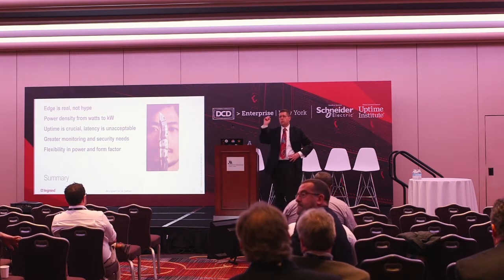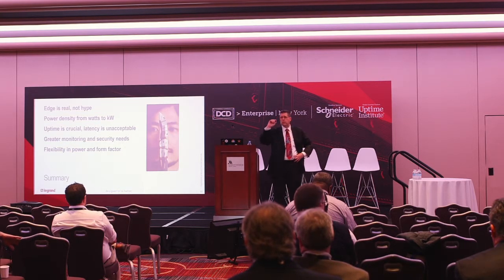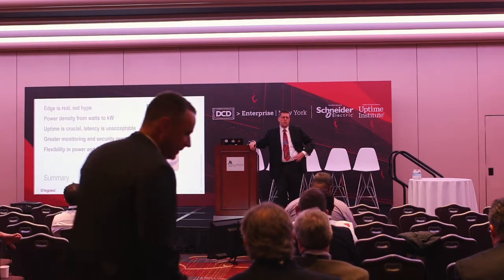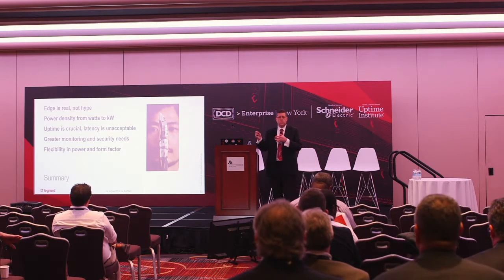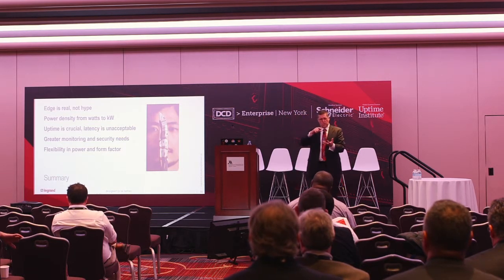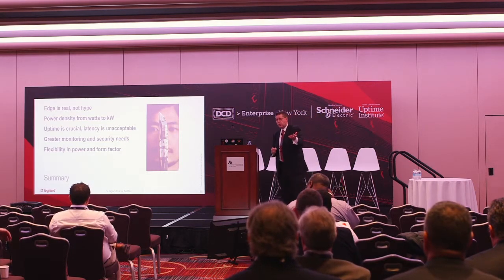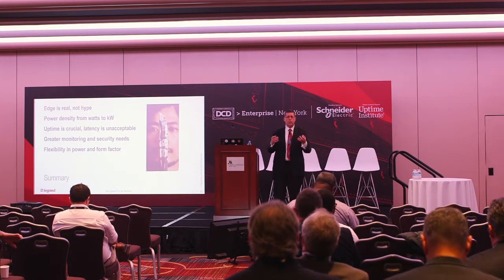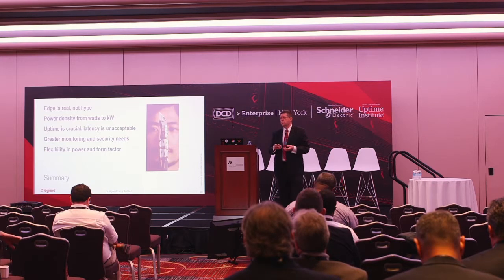So that was a quote from Bill Clayman, and that was part of a prior webinar that was done on the Raritan side of our house. Bill's data, as I understand it, comes from looking at a number of different edge type configurations. Vapor and Crown Castle, what they've announced is a 6-rack location with 150 kilowatts, okay? Roughly 30 kilowatts a rack. That's based on an open 19 type of architecture. And that's very power dense because they expect to do some heavy duty compute and storage in those racks.